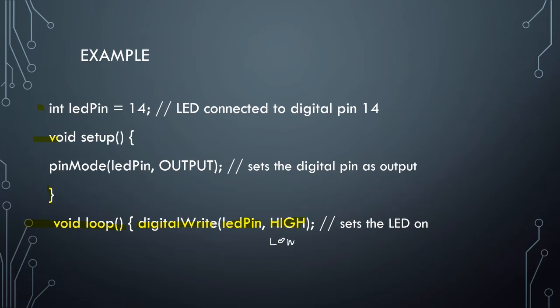And so here you can see we are building with our label. We have LED pin referenced in two places in our code now. If we needed to switch pins and change this to pin 12, instead of having to do that in two different places and try to make sure that we have everything and read through our code, all we would have to do is change this at the top. Everywhere that we're referencing LED pin, it would just circle back to the beginning and say, okay, I know the LED pin equals pin 12.